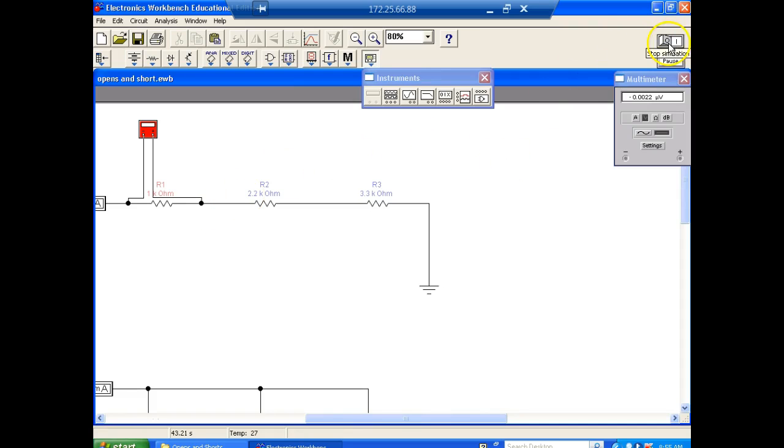So we'll come up here and turn it on. If it was on. 0.0022 microamps, or it's reading, that's microamps, right? So that's the best simulation you can do. Microvolts, I'm sorry, microvolts, because we're reading both. So when you've got a short circuit, this is one way you can find it. You can measure the voltage drop across there. A short will drop no volts.